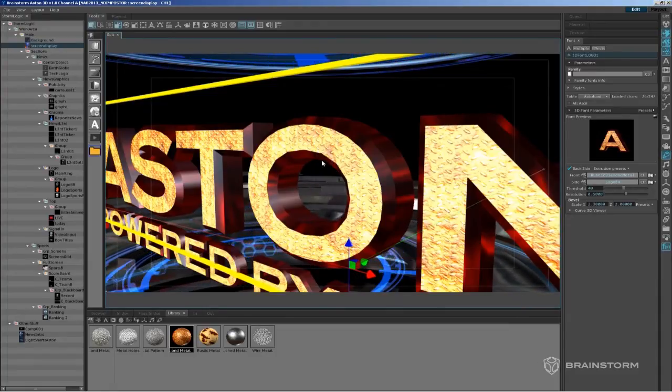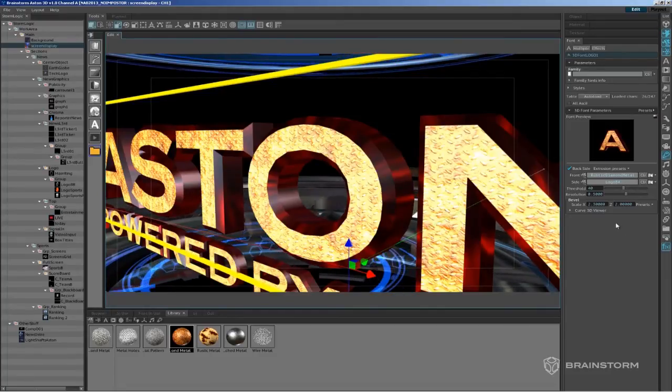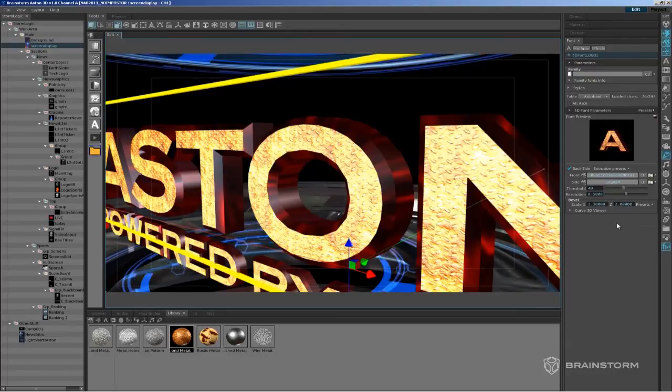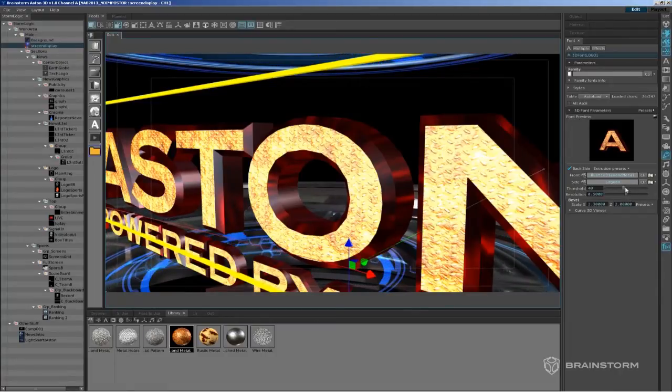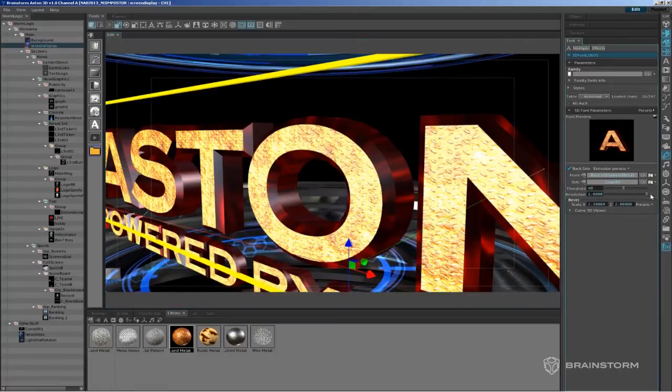In this case, you can see the transition, and that's because we have some controls to decide the quality of the render of the 3D elements. So we have these controls here, these threshold and resolution controls. We can increase, for instance, the resolution, and you see that now it's rounder.